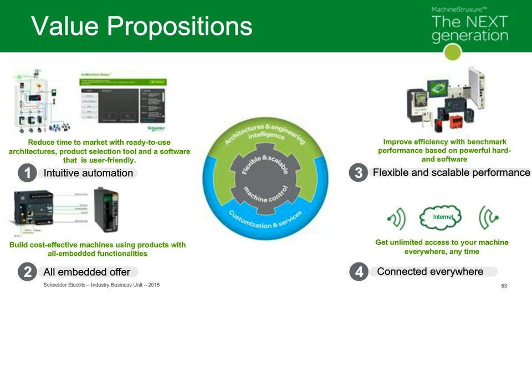By embedding all the separate functionality, like pulse train outputs with S-curve capability for smooth ramp up and smooth ramp down of your simple hardwired motion, all within the hardware itself, all really help to have the embedded offer. So you're allowing to ultimately have more flexibility and scalability in your performance, being able to be scaled all the way through our hardware platforms within one software suite.